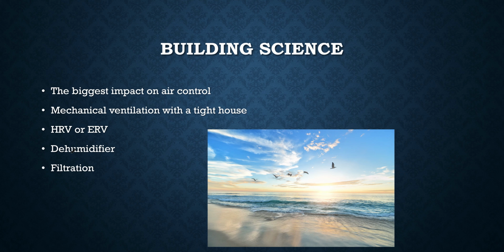So a heat recovery ventilator is a device that's designed to go with your ventilation system that exchanges the heat energy between the incoming and outgoing air. So it's like a little heat transfer device that crosses streams. It's not actually mixing the streams, but it crosses the streams in terms of their flow and allows them to transfer the heat energy from one to the other.